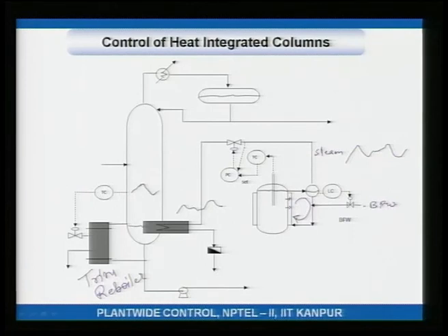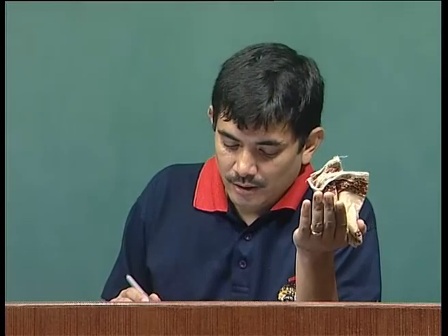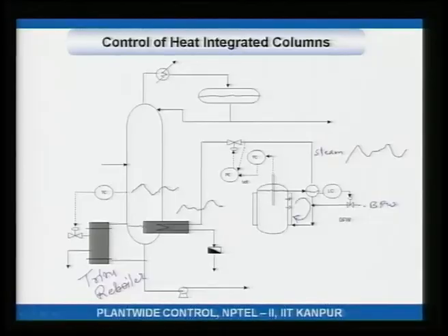So, what it essentially means is, because the steam from the reactor is varying, that creates variability in the temperature. Okay. The temperature must deviate before the trim reboiler can reduce or increase or adjust the reboiler duty to get that deviating temperature back to its set point. How do we overcome this problem?